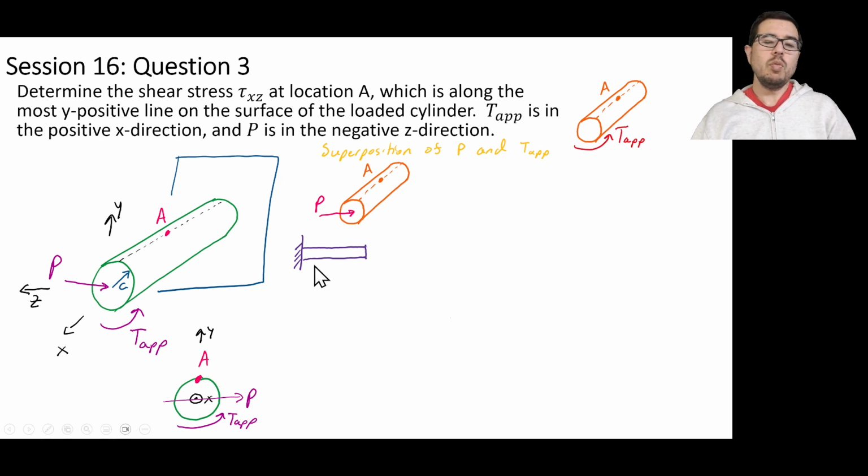And now, which way is this beam facing, and what is its orientation relative to the x, y, and z coordinates that we have in the initial problem? So we're going to define that x is still going along the axis of the beam. So here's a longitudinal axis, and we're going to say that y is coming out.